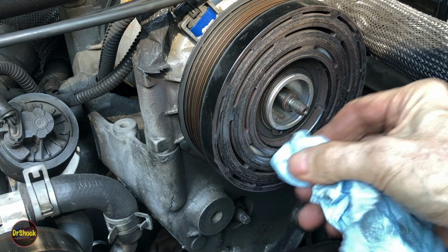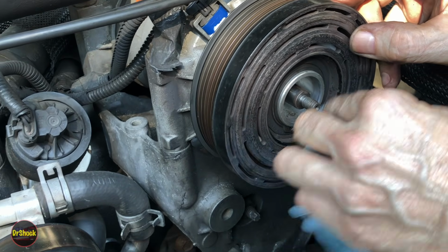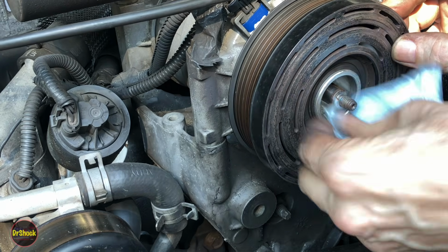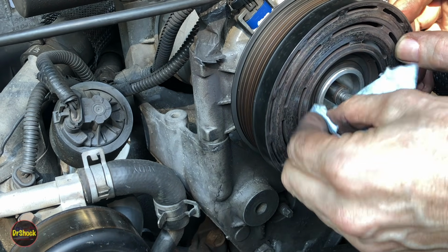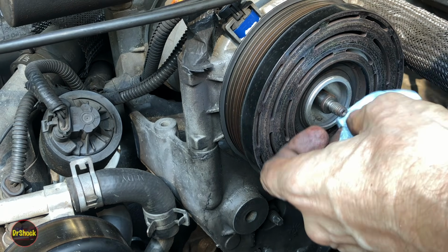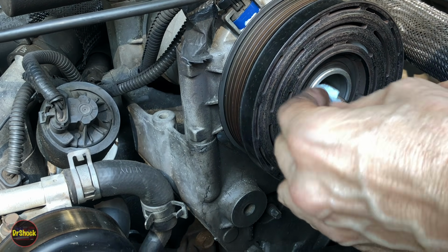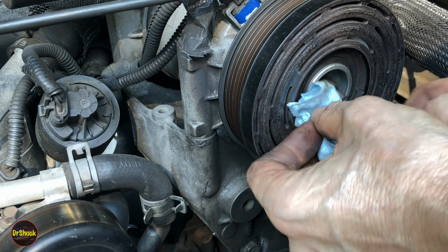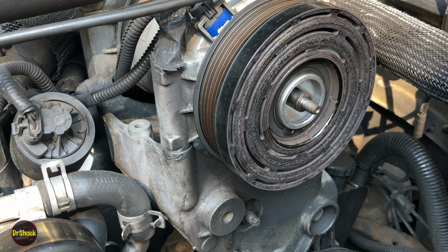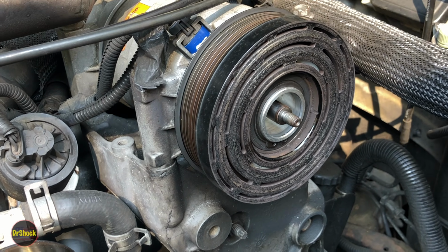We got a little bit more debris that got shook out by hammering, and some debris that shook out inside this bore for the clutch piece. So we're going to get that out of there. All right, and then the same thing we did previously, we're going to lube up the hub that goes in.